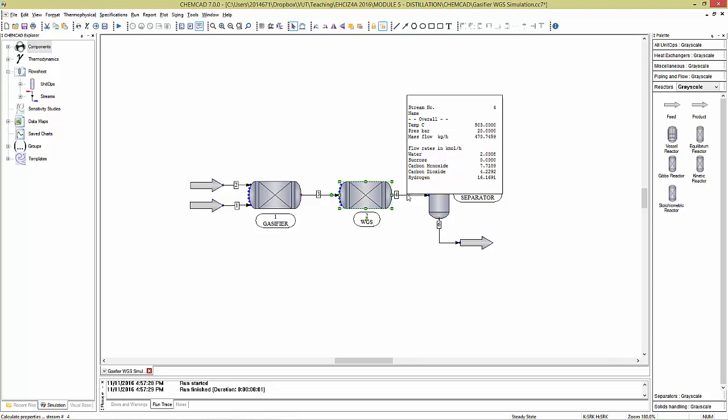Don't go below, because then you'll have excess carbon monoxide, which I would not really want to end up with in my reaction stream. I'd rather prefer to end up with excess hydrogen in my stream. But you don't have to worry about fine-tuning it to be exactly 2. Just get it slightly above 2, that will be fine.